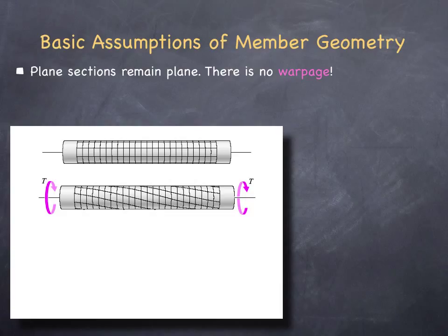on it with perpendicular angles between the vertical lines, the circular lines, and the horizontal lines. If we apply torque to it, the vertical lines that represent a cross section will remain vertical lines. The circle will not have a larger or a smaller circular cross section. These circles won't warp out of their plane of deformation. The only thing that we will experience here is that those 90-degree angles of our grid lines will turn into some other angles depending on the magnitude of the forces applied.